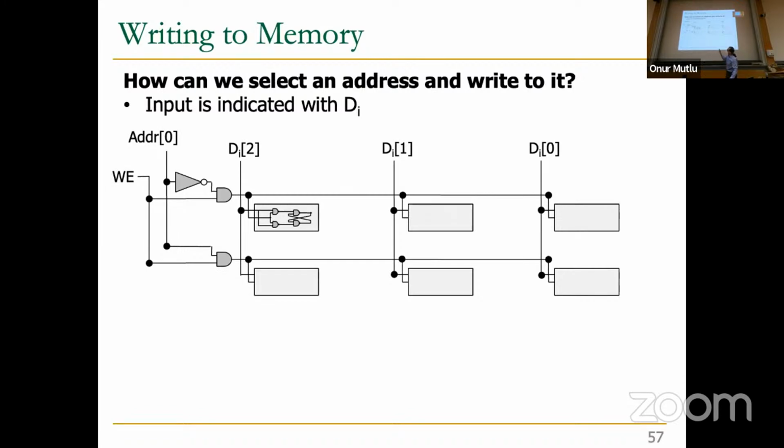Basically, if this address is 0 and write enable is 1, then the data value propagates into the output over here, just like we've seen in the operation of the D latch. If this address is 1 and the write enable is 1, then the data value over here gets written here. We've already seen the operation of the gated D latch. That's how it should operate. And again, because the write enable is ANDed with the address value, that's how you ensure that this is the write enable signal of the gated D latch.